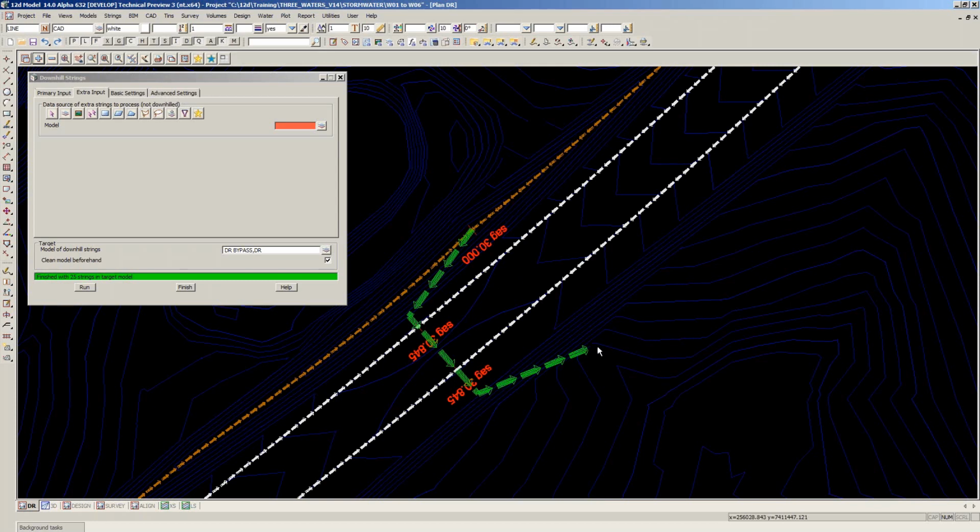But the green string I've drawn in this case for the culvert is going to represent if this culvert ever needs to overtop the road, the water's going to rise up the embankment here, and this is the spill point, which is the low point on the road surface. It'll actually go across the road there and then spill back to the overland channel, or the cross channel, and go wherever it goes.